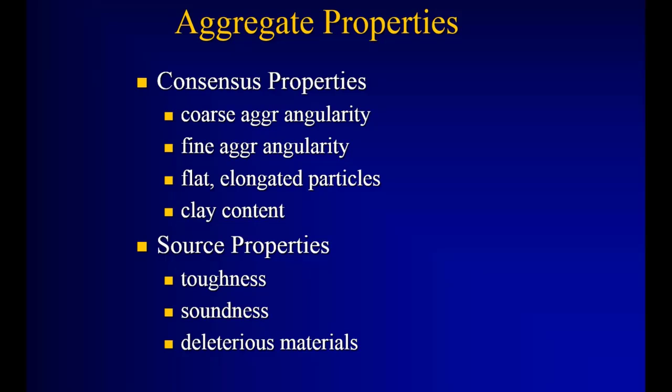So there's a lot of history now, particularly once the Bakken formation hit, that Superpave mixes perform well in the highest traffic applications, probably in a 6 or 8 state area, when all the heavy truck traffic hit, you know, the western 18 counties, shortly followed by all the counties in North Dakota. And so FAA, or fine aggregate angularity, we'll talk about that a little bit more, but was a really important feature.